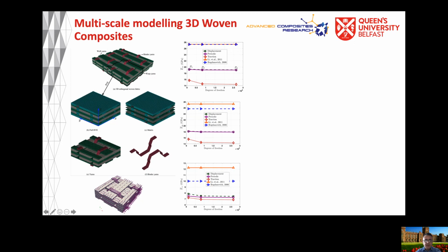So as you can see in this figure, in the 3D woven composites, we have yarns in this case oriented in all 3 directions. So the green yarns are in Y direction, the gray yarns are in the X direction, and we have these red yarns which are in the Z direction. These 3D woven composites will provide you with very good mechanical properties in the thickness directions, including fracture toughness, very good impact properties, and very good mechanical strength.